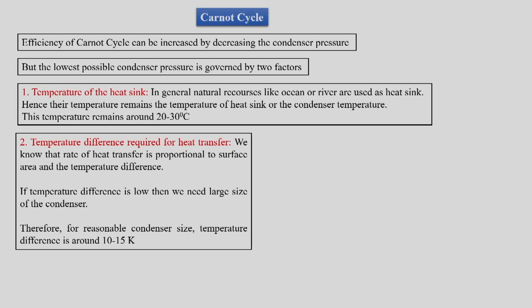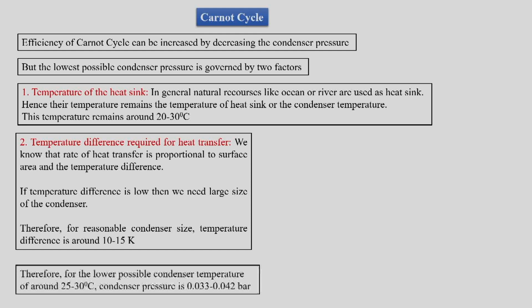We had discussed that the direction of flow of water in the condenser does not alter the irreversibilities, but if we try to keep the temperature difference between the natural resource water and the steam to a minimum, then we will have a very large area to be supplied for the process of condensation.